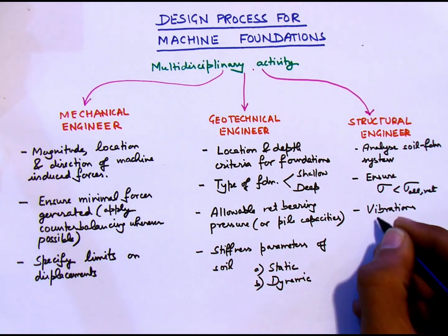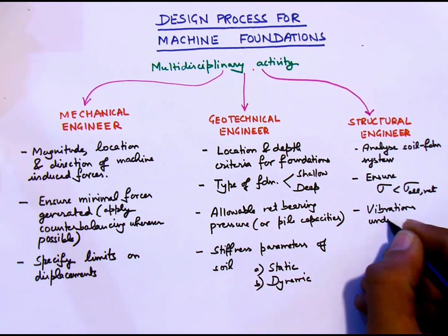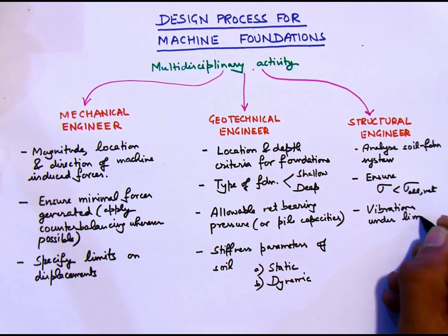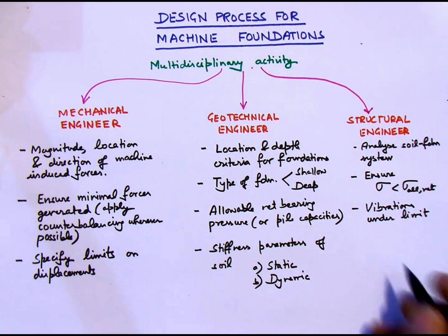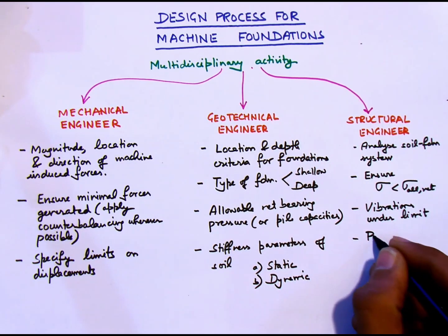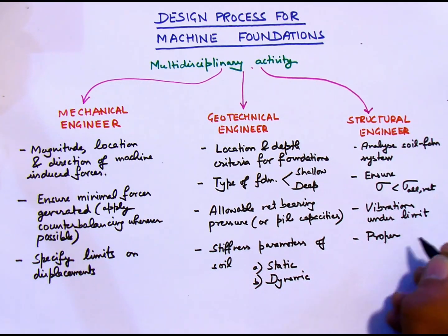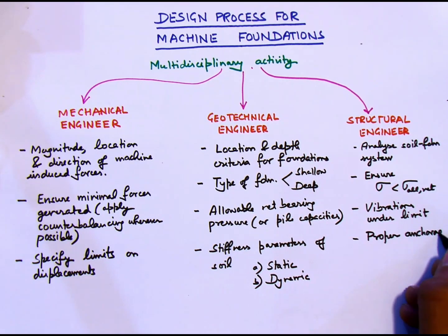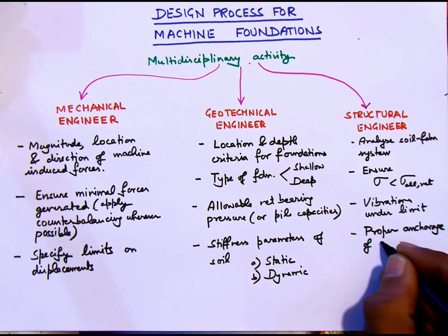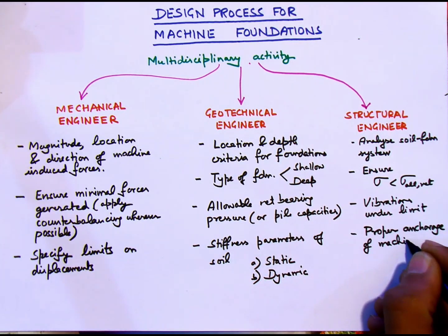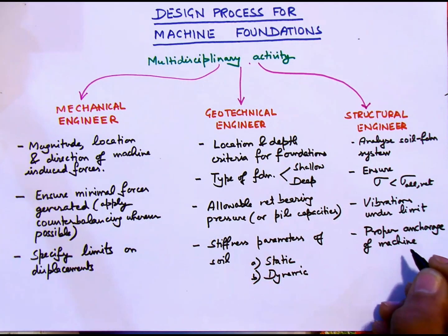Under limit means that they should be less than those specified by the mechanical engineer, that is the manufacturer, and they should be within the limits to ensure safety of the structure as well as comfort of the user. The structural engineer must make adequate arrangements in the concrete of the foundation so that the machine can be adequately anchored.